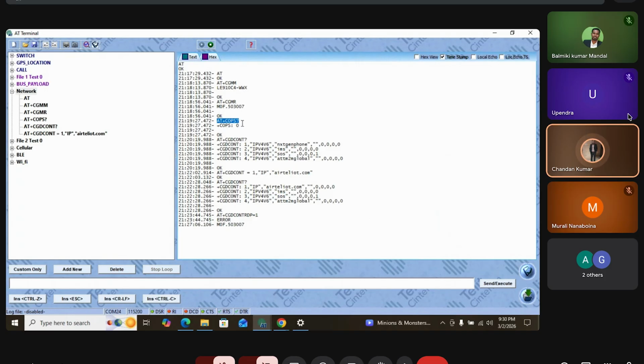When I use my mobile phone SIM card from the next classes, depending on our project, then it will give an AT+COPS response of Airtel, BSNL, Vodafone, anything. Whatever SIM card I am using, it will give its name. Okay.